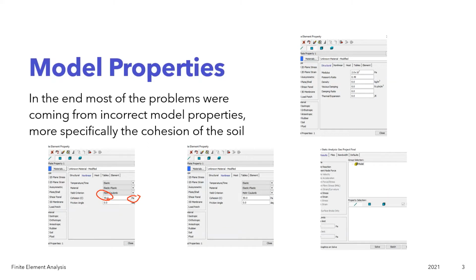That was because of incorrect units. Because of this, the model wasn't converging and it was taking really long to run. I think that's because it was making really big deflections in other areas in the model, so the model wasn't getting a chance to converge properly, making it take a really long time to run. Once we fixed that, the model ran faster and converged, so we moved that change to the rest of the models and ended up getting some good results.